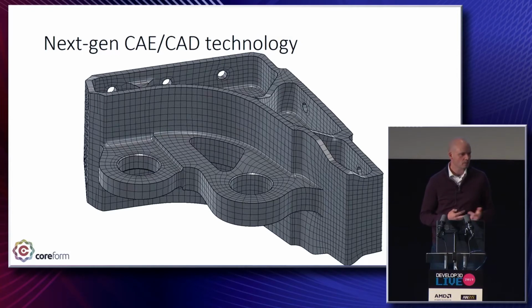This was my former company. I sold it to Autodesk, and here's an example of a complex T-spline part modeled in Autodesk Fusion 360. Some of the benefits of T-splines are the ability to have T-junctions or hanging nodes, extraordinary points, creases and sharpness in the same model. U-splines takes us to the next level, whereas this is one single degree 3 T-spline. With U-splines in a single model, we can have degree 1, degree 2 to have exact fillets, degree 3, arbitrary